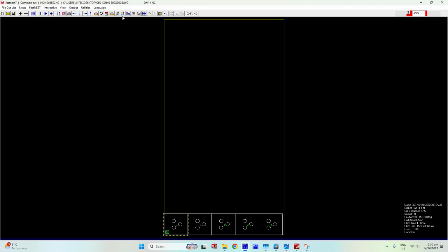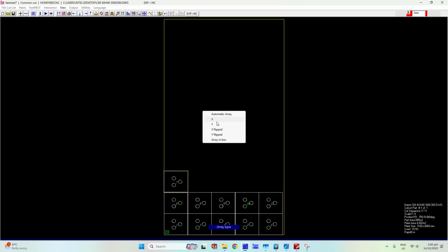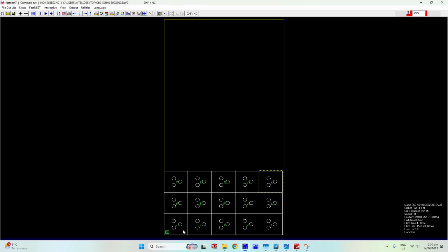And we just keep patterning until we get the number of rows that we want. So it's another 3 more rows. Enter Y, okay, and we put 5, enter X. Now 5, enter X. Now if you zoom in, you can see the order is jumbled. To rearrange it, you just go to resequence, then we put a row snake. So you should see 1, 2, 3, 4, 5, 6, 7, 8, 9, 10, and so on.